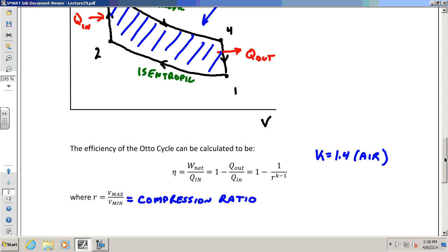But diesel, which doesn't have spark plugs, takes advantage of it and says, who needs spark plugs? We'll just design these things to run higher compression ratios, and we'll just let it go on its own. And we get more power. Diesel is really making a comeback, because you see things like the Volkswagen Jetta running diesel. It's a cleaner diesel now. We've learned how to get it cleaner in terms of exhaust management, and we've gotten more power per stroke because of higher compression ratios. That's why your big trucks are all diesel.